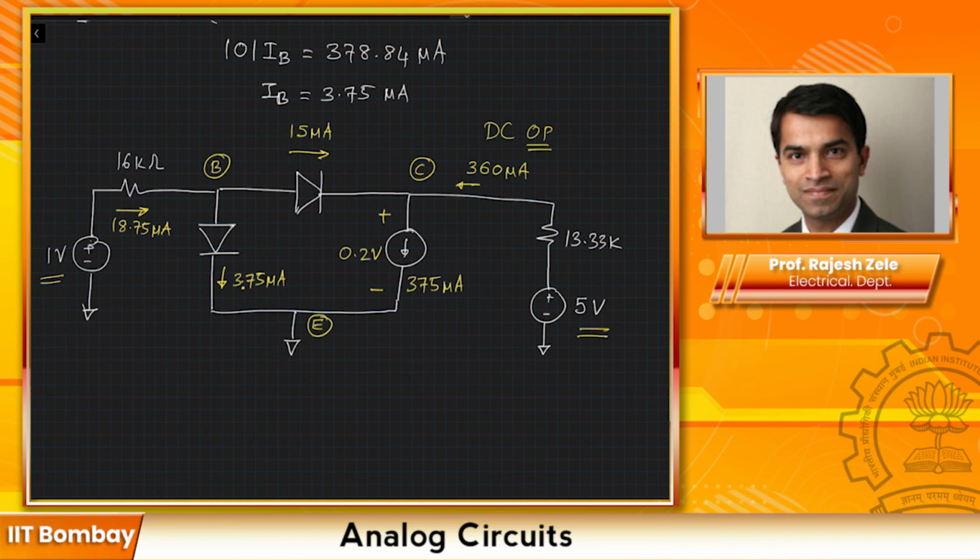In the lecture notes, I would like you to go through and follow the same exact example for PNP transistors. That will make you more comfortable. Pretty much what we have gone through today is one simple example. I have taken you from a transistor which is totally turned off, to a transistor in active mode, to a transistor in the saturation region. Our most favorite mode of operation is going to be the active mode, because that's where we are able to get small signal gain from the device. That's to keep in mind.